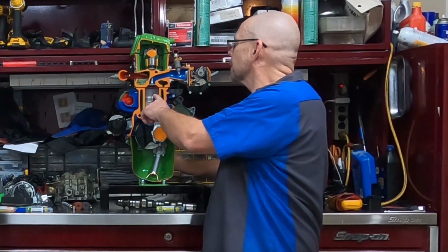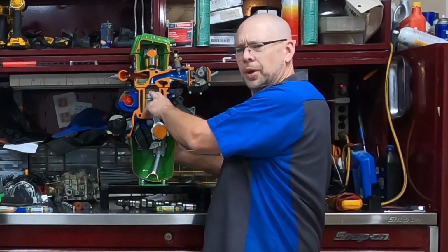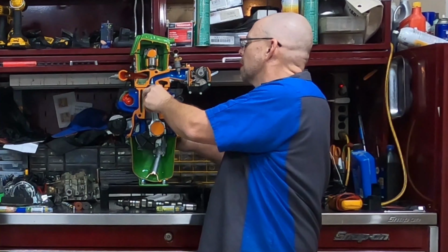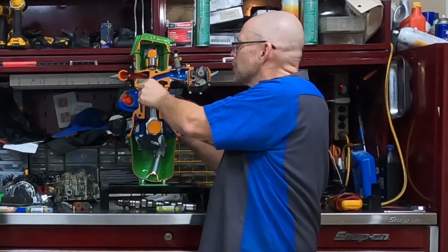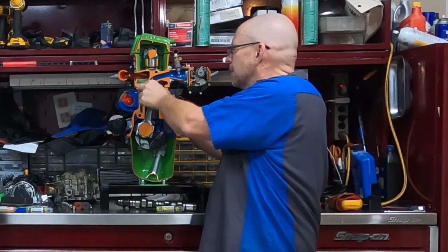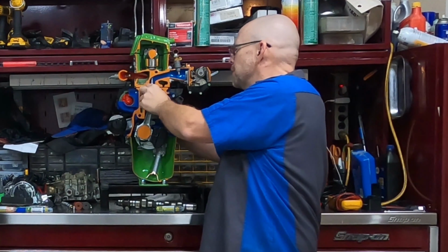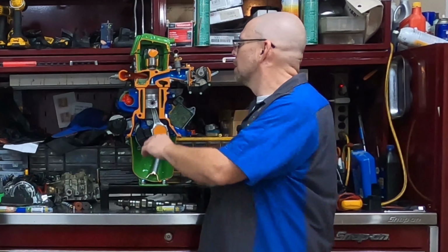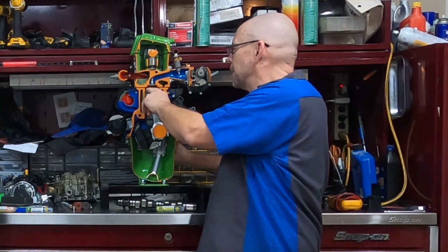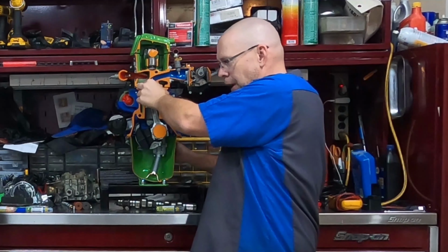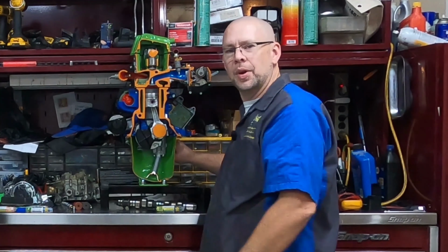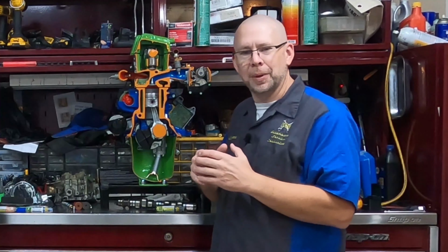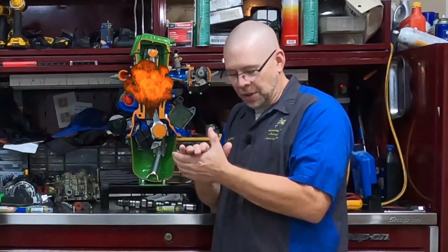If we're coming up normally, and say we're going to ignite this at 20 degrees before top dead center. It comes up, it ignites, we're still moving forward, we're still compressing, even as it's igniting and burning. We get a nice even burn. It finishes by 10 degrees after, and we put lots of force on the piston. Now, we up our boost. Pressure's much higher in here. Piston's coming up, we ignite the spark plug, it fires off, but now the pressure's so high that we have pre-ignition or auto-ignition. It doesn't have a nice propagation or burning of the flame front, it just explodes.